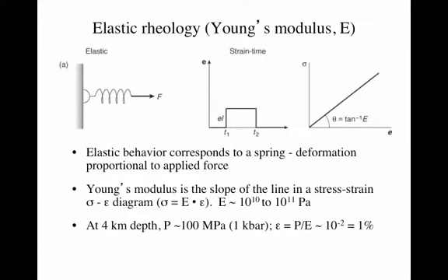If we look at elastic rheology, we have to consider Young's modulus, which we'll use E to stand for. Elastic behavior corresponds to something like a spring, so the deformation is proportional to the force that you apply to it. Young's modulus is the slope of the line in a stress-strain diagram as above. In that diagram, Young's modulus is about 10 to the 10 or 10 to the 11 pascals.